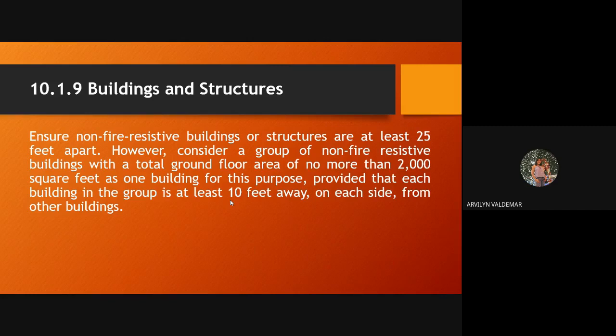However, consider a group of non-fire resistant buildings with a total ground floor area of no more than 2,000 square feet as one building for this purpose, provided that each building in the group is at least 10 feet away on each side from other buildings.